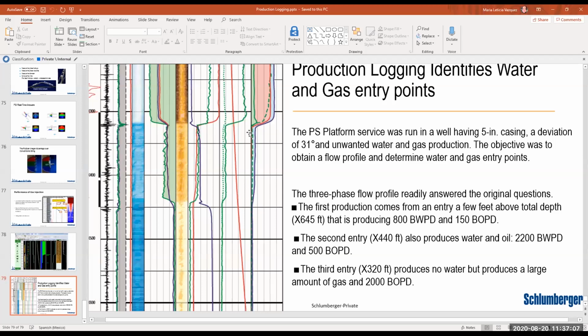So there is no real input of water from the top perforation, but mainly from the bottom perforation itself. You have some water entering the system from the bottom perforation, and some hydrocarbon as well. But the top perforation is your main source of hydrocarbon, and only part of the top perforation.